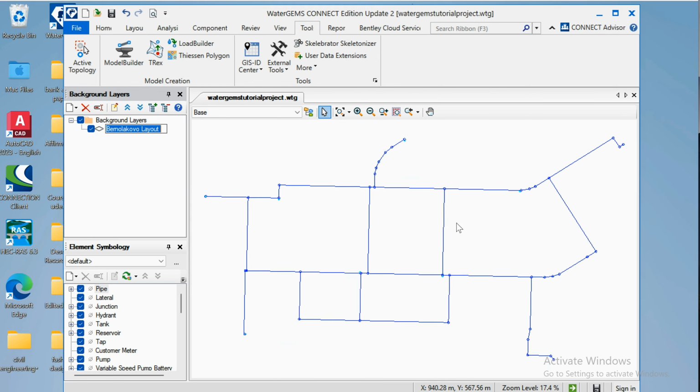Perfect. Basically, if you have your maps in different AutoCAD files, you need to also insert the rest of them. So you also need to put there your contour map. And if you have your nodes alone, the reservoir alone, and the road network alone. Okay, so after I apply my background layer of my network like this, I can already start off with drawing the pipes and the junctions. But beforehand, I want to say something, okay?